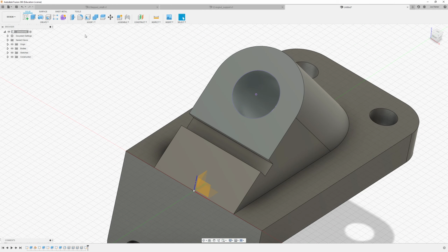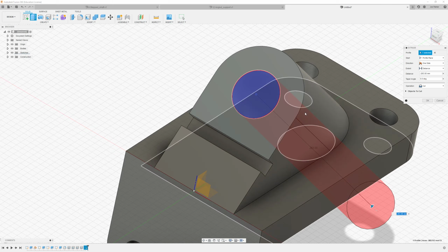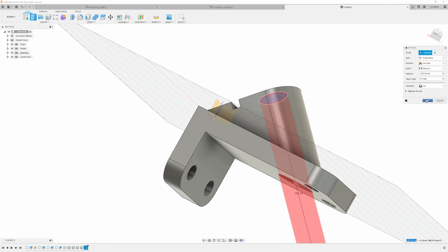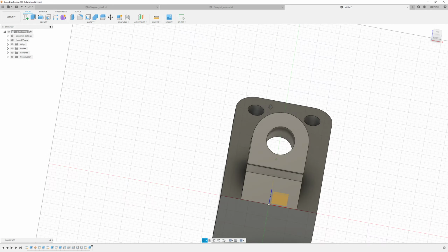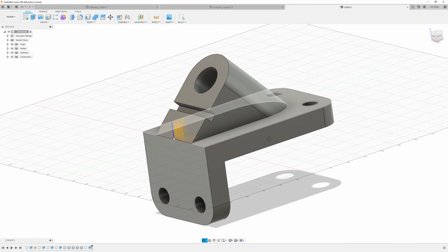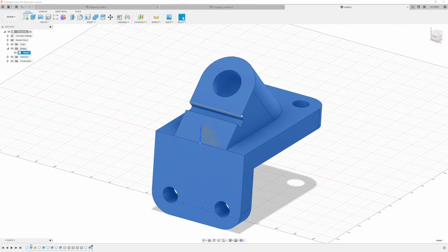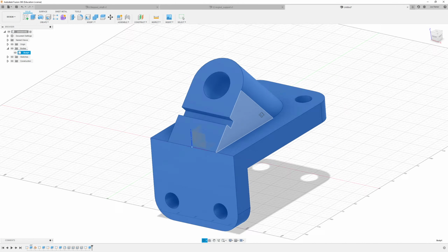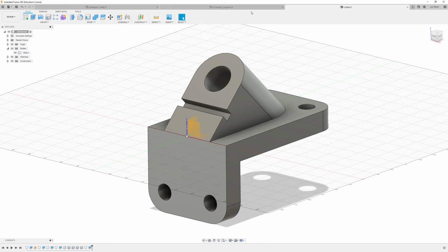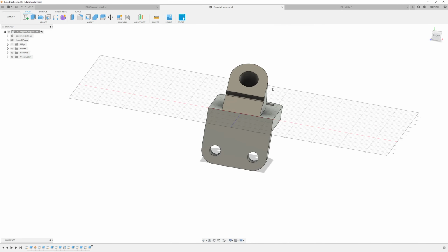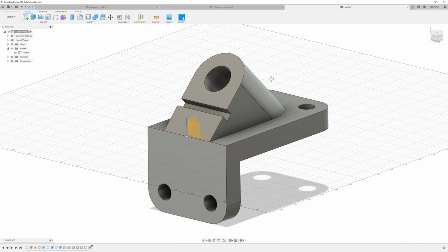and then we are going to extrude that all the way through the component to ensure that we have a hole running all the way through the component. I'm happy with that now. As a final check, I'll just have a look at the number of bodies I've got in my component. I can see that I've only got one body of material, and that is the entire component. I can tell that the geometry is identical to the reference component, so at that stage we are finished.